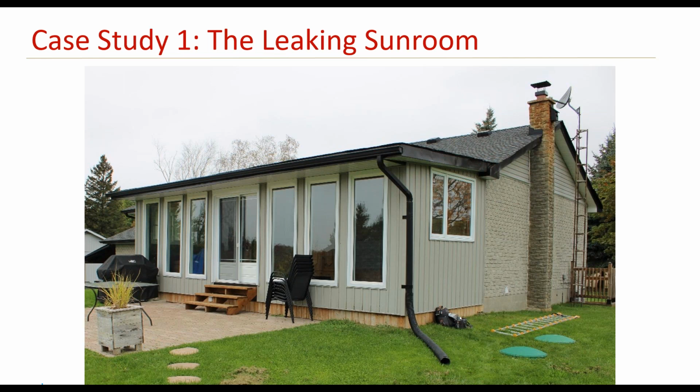When I first arrived on scene, I realized that the roof slope here was shallow, and the roofing material, which was shingles, is not the code compliant material for such shallow roofs. So that was the first observation. The second thing I noticed was the chimney flashing that was not done properly.